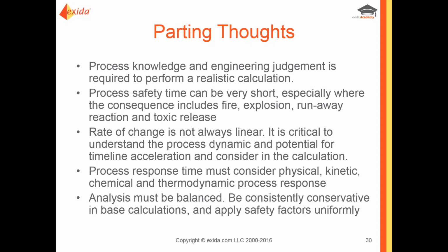When we're looking at the process response time or the SIF response time, we have to consider all of the physical, kinetic, chemical, thermodynamic responses of the process. Some of these things can be fairly slow, some of them can happen quickly. We need to look at those in determining that tail end piece after the SIF has finished its task until we actually turn the process around and have achieved that safe state. Have to consider that lag. It can be very significant.